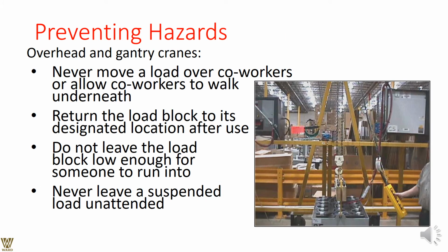We can prevent hazards by not moving a load over co-workers, or allowing co-workers to walk below the load at any point of time. We should return the load block to the designated location after use. More often than not, the worker, after finishing his or her shift, dumps the load the way it has been, with the crane stuck out there, on the pretext that they will continue the work the next day from the point they have left. It is always better to get everything arranged properly, docked and locked altogether.